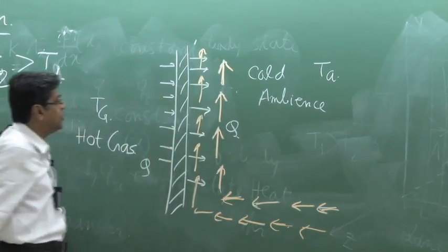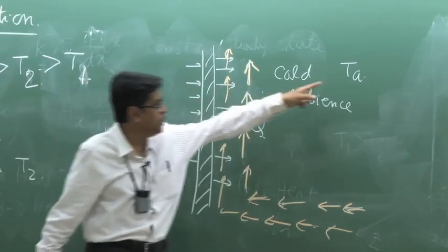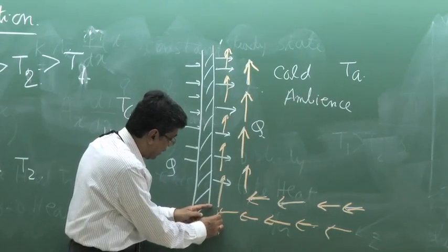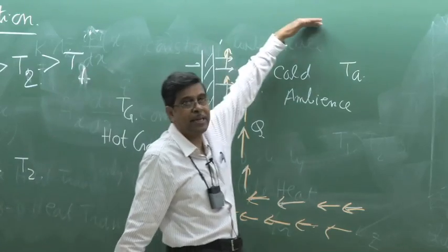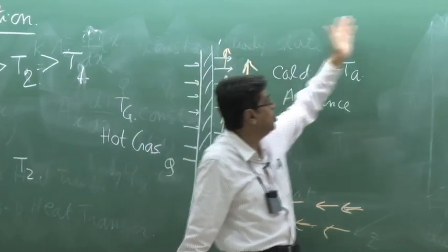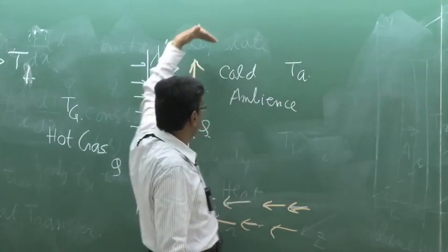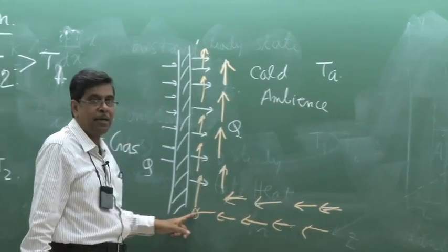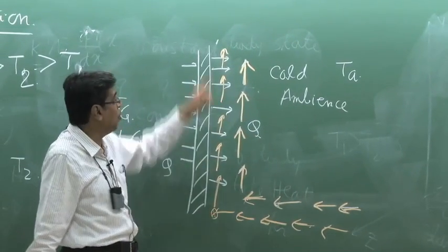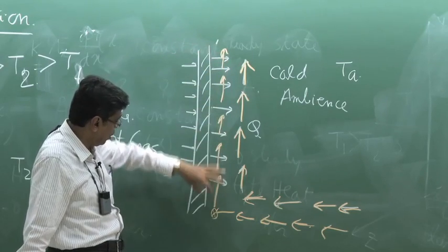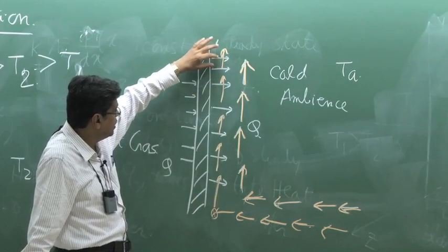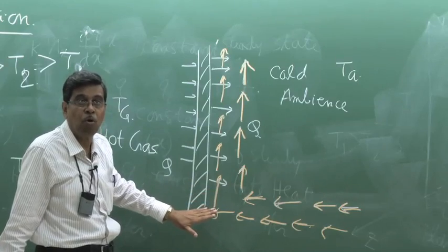How? You see, since this is hot compared to this, at any point here, if you consider the pressure at any high altitude, it is the same at these 2 points, the same elevation. So, pressure here represents a pressure over that atmospheric pressure by a height of the column whose density is at high temperature, density is low.